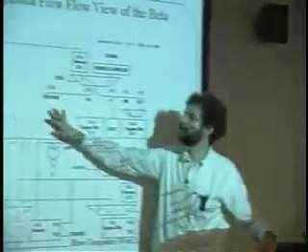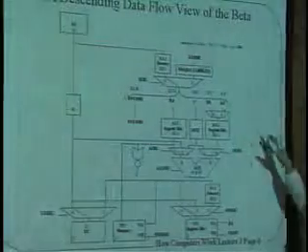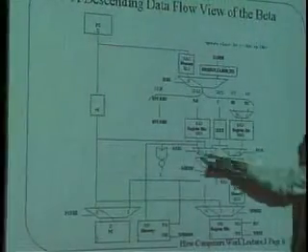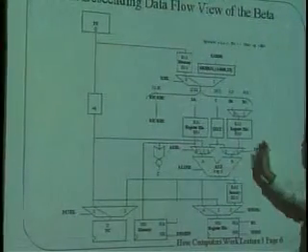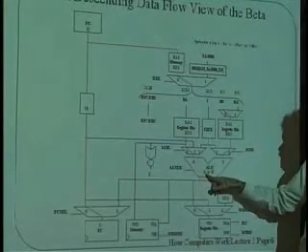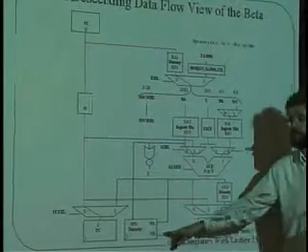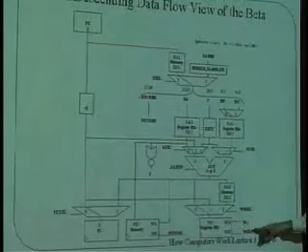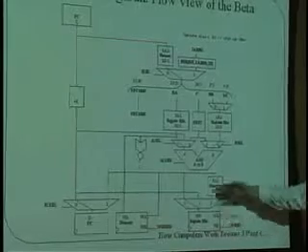So the opcode controls that? So in the end, yes, the opcode will control everything. The opcode will be decoded by some control logic on the side, and will control how each of these selectors is told what to do. It'll control the ALU function telling the ALU what to do, and it will also control the memories down here, telling them whether or not to pay attention to the clock and to store something new.